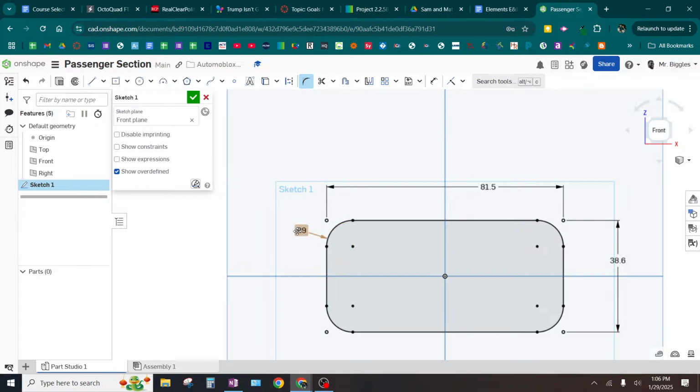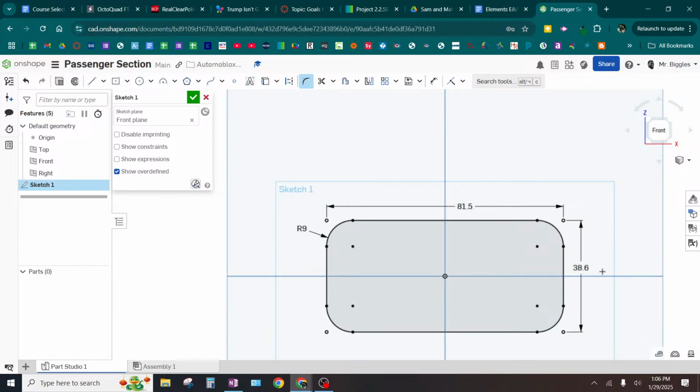Now, one thing I would do is I would be intelligent with where you place your dimensions. I would place them in an organized way so they're not like this. See how that number is covered by part of the symbolism for the dimension? That's not good. All right. Usually you want them in the middle or something like that. You don't want them right on lines and stuff like that. That's really hard to see the number. We don't want that. Okay. We have questions before we move on?